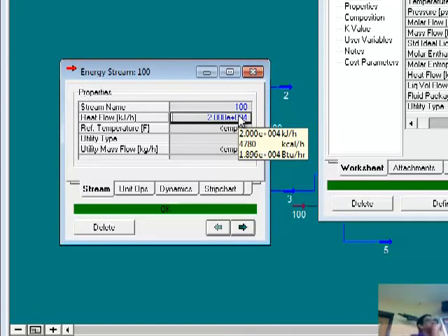You can't specify the molar flow rate in stream 4 and then have it tell you how much heat to put in. You can do that with an adjust block. Right now, you give the input and it calculates the output. So if you want to specify something on the output stream, then you have to use this so-called adjust block.